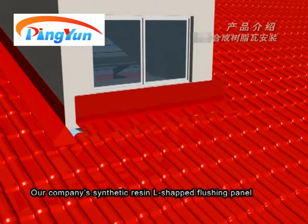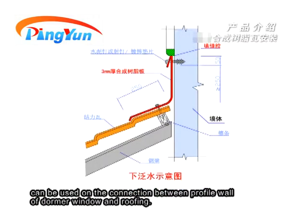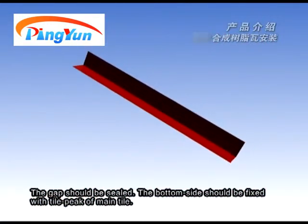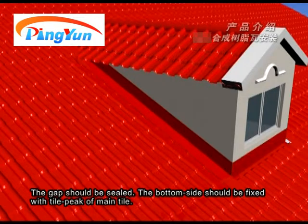Our company's synthetic resin L-shaped flushing panel can be used on the connection between the profile wall of the dormer window and roofing. The upside of the L-shaped flushing panel should be fixed on the side wall of the dormer window. The gap should be sealed. The bottom side should be fixed with the tile peak of main tile.